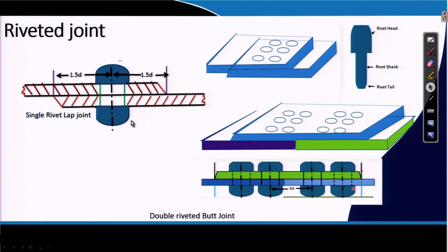If you have seen the Howrah Bridge, you might have seen that a lot of protruded portions are coming; those are riveted joints, made in the early 20th century. That type of bridge was constructed and is still going strong. Why exactly are those bridges riveted, not welded? Because bridges undergo a lot of vibrations.